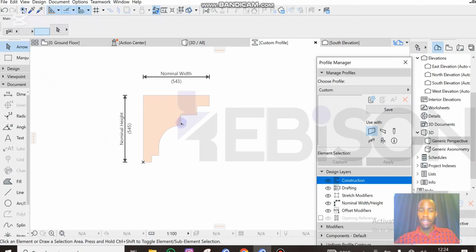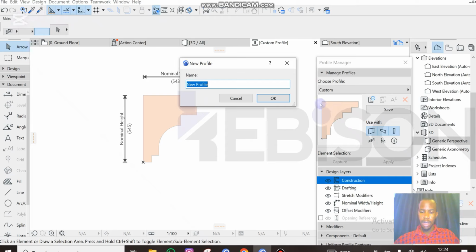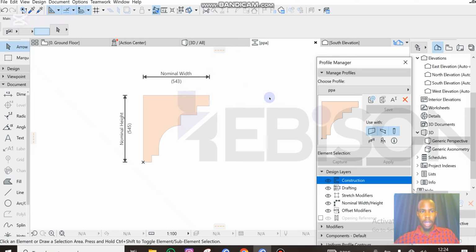You want it saved as a wall or a beam or a column. So you just click on the column like this, I like the column like this, then you save. And you name it. I already have parapet already, so I'll name this as TPA. So I'll press my OK. Then I can let go of this, so I can still leave this. Doesn't really matter.